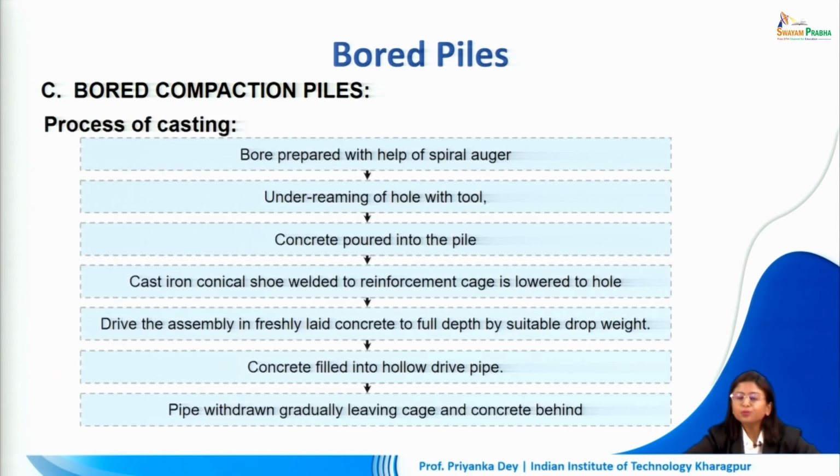So what we are going to do is the bore is prepared with the help of the spiral auger. So pretty similar to what we did in the underream pile. The underreaming tool will be inserted. The concrete will be poured into the pile.